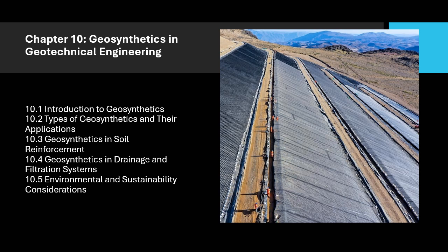In landfills, geotextiles are used as filters to ensure that leachate flows through the drainage system without allowing fine particles to enter the underlying soil or groundwater. Geotextiles can also be used to prevent the mixing of different soil types in landfill drainage systems.